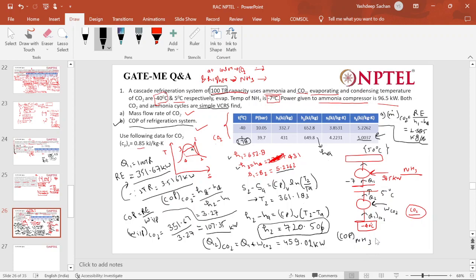So COP of ammonia system is what? It would be the Q1 of ammonia divided by W of ammonia. Q1 for ammonia is 459.02 and the work for ammonia compressor is 96.5. So what is the COP? 4.7567. Yes, sir.